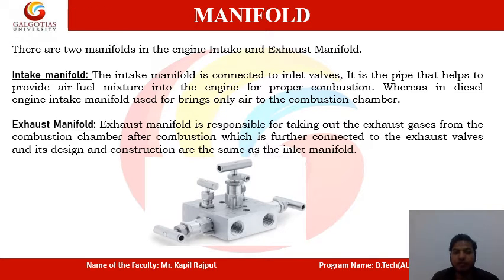Now coming to the manifolds. There are two manifolds in the engine: the intake manifold and the exhaust manifold. The intake manifold is connected to the inlet valves. It is the pipe that helps to provide the air-fuel mixture to the engine for proper combustion. Whereas in a diesel engine, the intake manifold is used to bring only air into the combustion chamber. As you know, the diesel engine uses only air in the suction, whereas in the petrol engine, the mixture of air and fuel is there for suction.